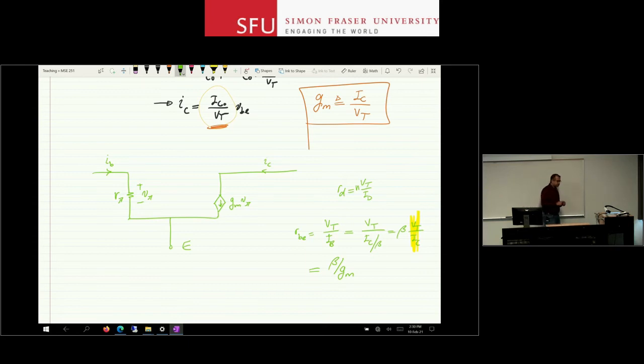So it really is not necessary to add the small signal and large signal to each other most of the time, because the DC part has a well-defined component. AC part, no, it is variable, it is changing. Usually we talk about ratios for small signal quantities.